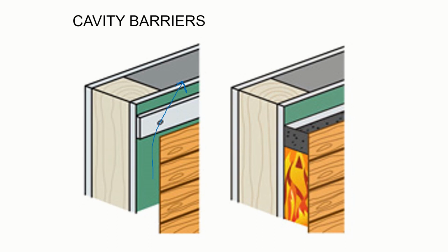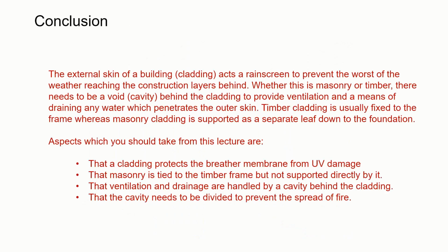So we can get either intumescent materials, which is this cavity barrier here, and under fire it's going to expand out, or we can use the bags from 2 slides ago, which are compressed mineral wool that when they burn under a fire, the bag gets removed and the mineral wool expands out, and there are some intumescent properties in that as well.